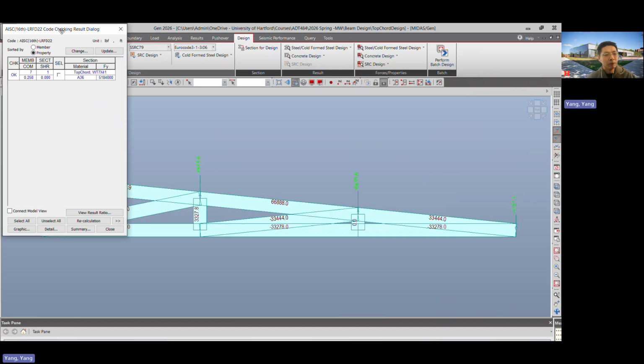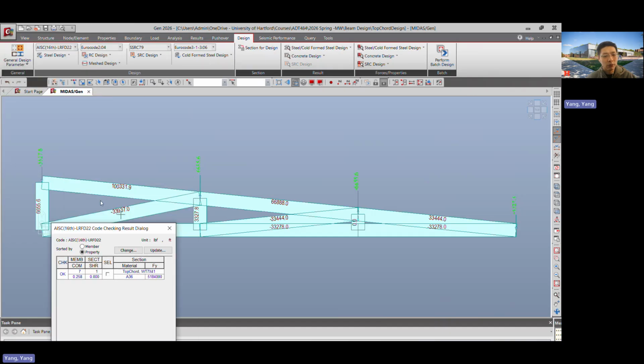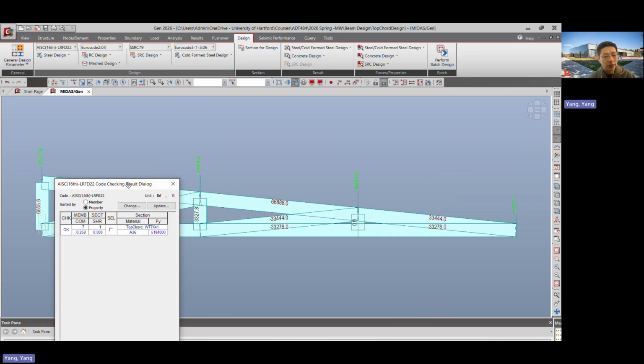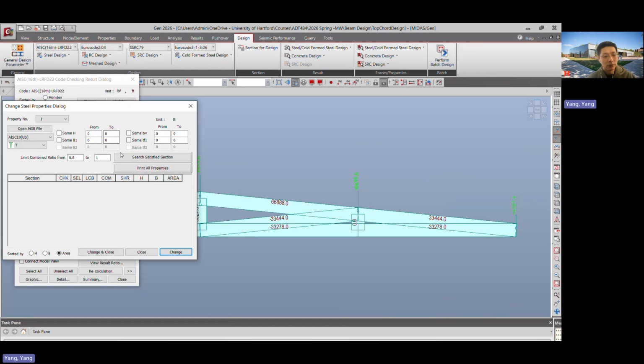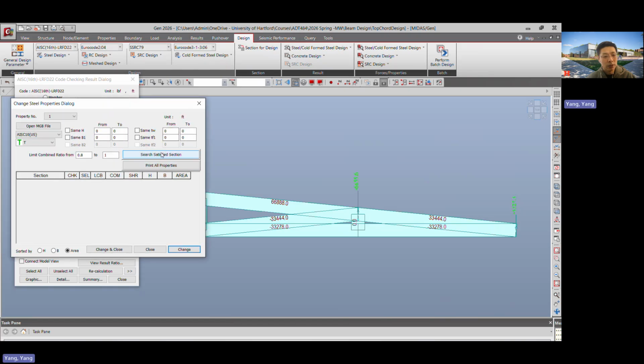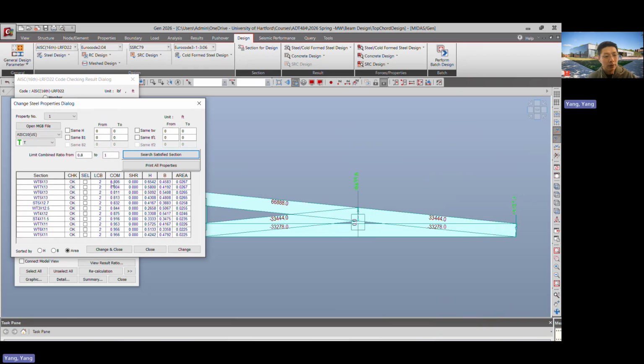So it looks like the WT works for all the cases since the controlling factor is very small, but we could change some of the design, such as we can select this one, we can change whether we can use a smaller, okay, such as we can have a smaller ratio, such as we could use the WT4x12.